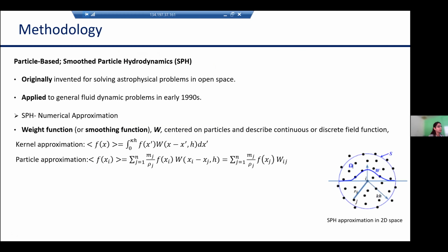To investigate the applied load on a bridge deck by debris, we use the novel coupled particle-based and finite element method. SPH is a Lagrangian-based meshless technique in which the continuum of a fluid is replaced by a set of non-connected particles. This modeling approach has two key steps.